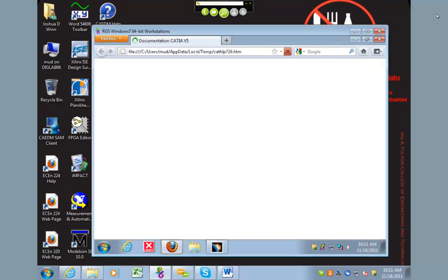And so the first thing you'll need to do in line 1, if you click in the box, is define where the Revolute is going to pivot. So if we zoom in a little bit, we're going to go ahead and grab this. Now this is really frustrating, so you guys will kind of have to move your mouse around a little bit. But eventually it'll bring up a line like that. Yep. So that center axis is going to be where it pivots. The second line will be the second joint and where it's going to pivot. And like I said, those are really hard to get sometimes. I find for this particular one, if you hover around this little edge, you can usually pick it up.